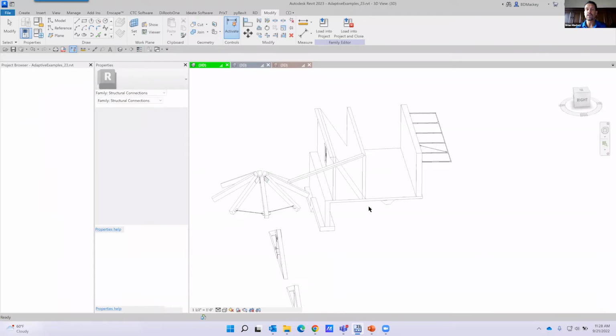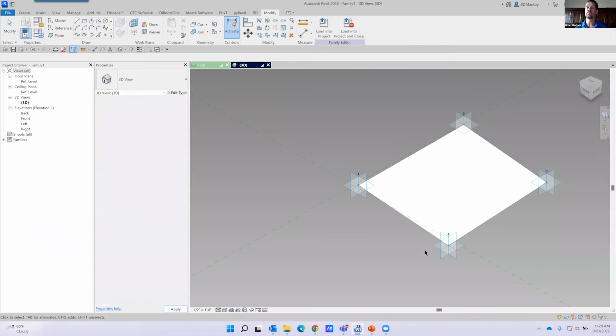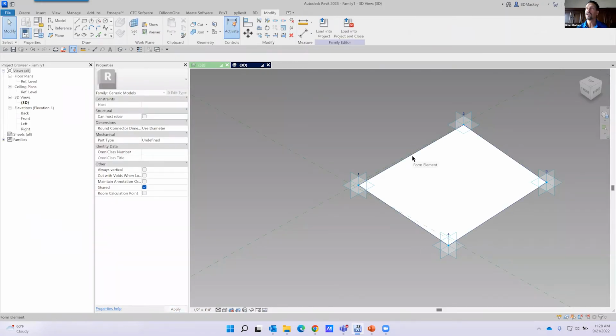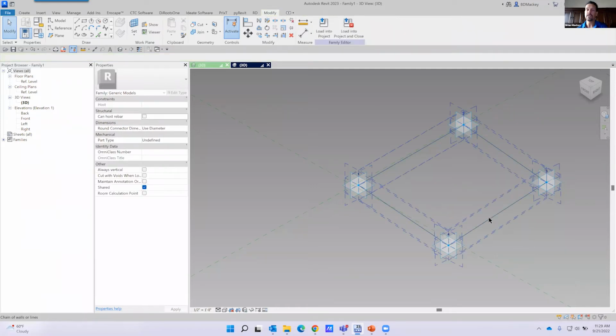you can see that now I came in here and I've created these little 4 points, and we start placing things off those points. If you create something like a surface and you want to remove it, you don't ever hit delete inside of here, because if you hit delete and you had done this with model lines, you would lose all of those model lines.